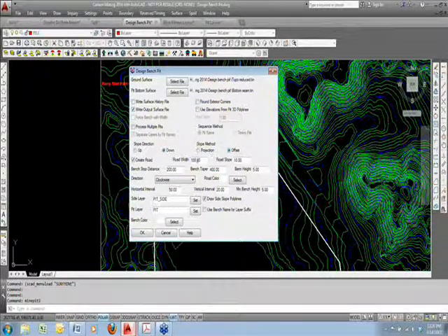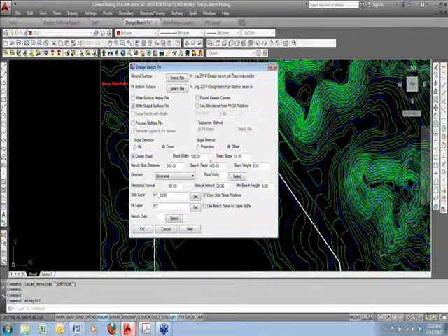Anytime you do the road or the ramp option, you have to go with the offset. That's the default. We'll put in our road width of 100, 10% slope. And here are some of the new options. It's the bench stop distance. I have it set to 200. The bench taper is 400. And these are just basically widths or lengths that you can see from plan view, and I'll show you those. The berm height, I'll just put in a 5. This is in feet or meters, 5-foot tall berm.